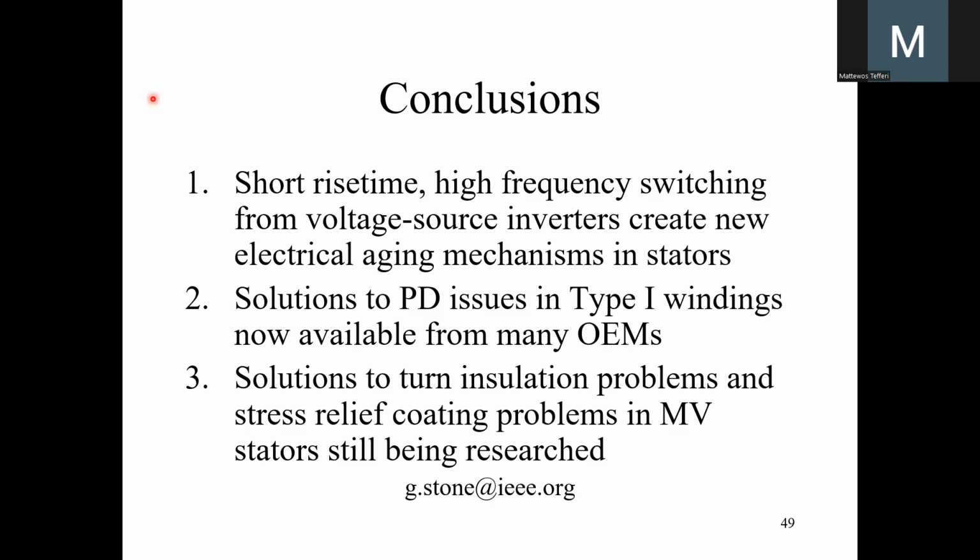The first question is from Okumu. Can the effect of inverters in PV plants affect the transformers in a way similar to motors and generators? Yeah, the short answer to that is yes, especially they tend to be dry type transformers. And so in many ways, they do look like machines. This is not my specialty, but I am aware there have been issues. So again, there's the non-uniform voltage distribution through the windings of a transformer, and therefore you can have PD activity where you would not normally expect it to occur.